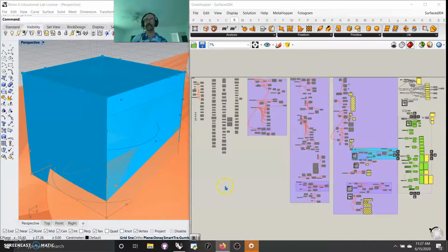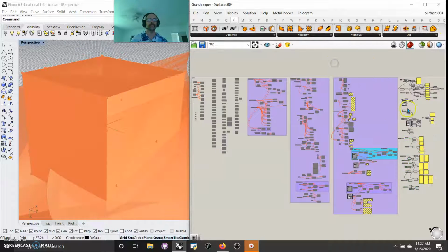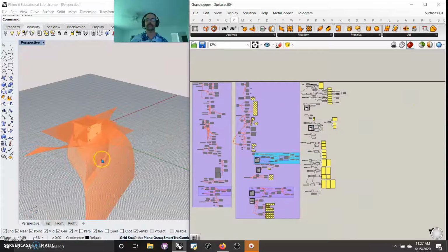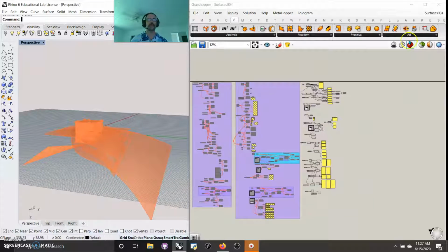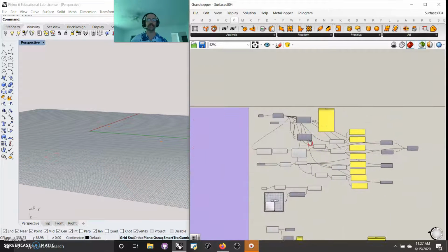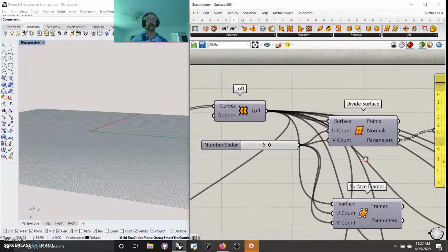All right, the ABCs 1, 2, 3 is a Grasshopper for Rhino. We're going to activate the last set of nodes in the Surface tab, which will be Utilities, and we'll run through and see what we can do with those. So let's zoom back out, keep in perspective, put it so we see what we're doing, and let's start with the first node, which is basically dividing a surface.